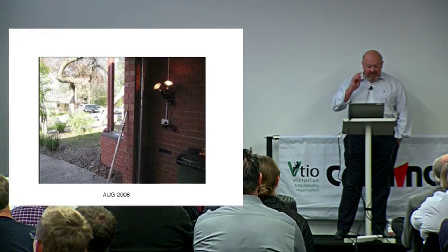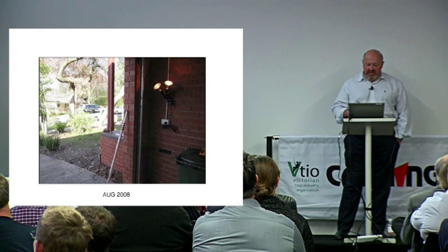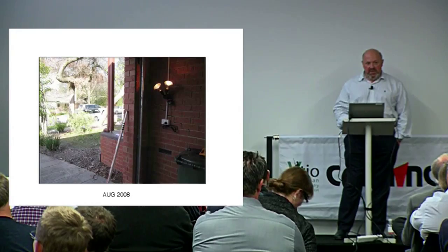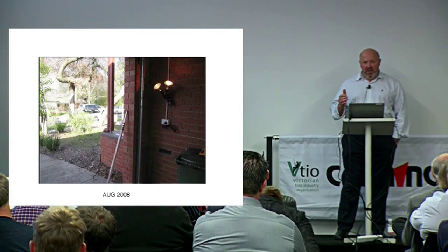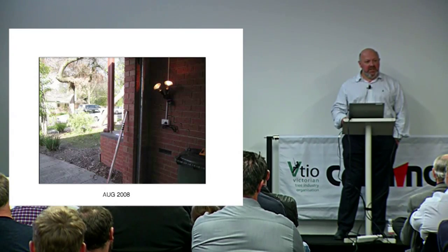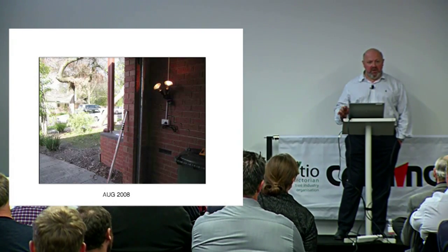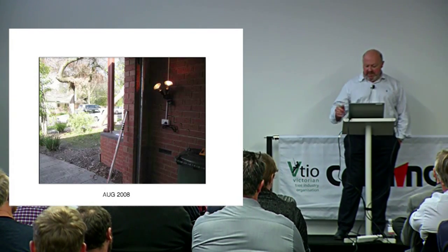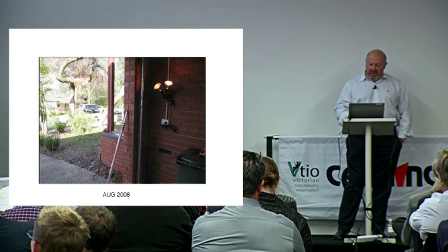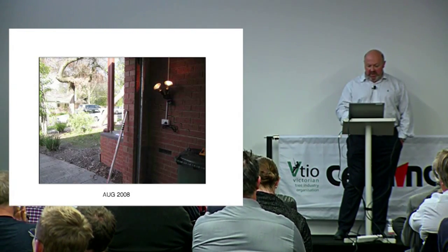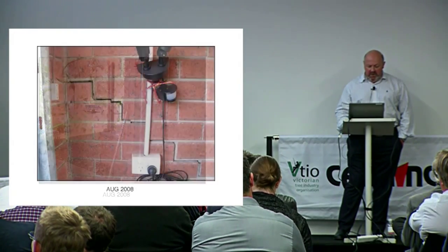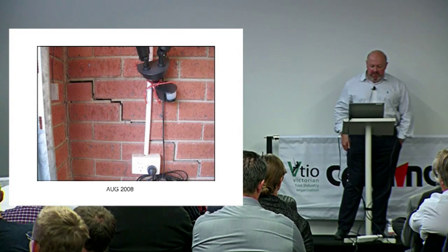Okay, this is just about finished. In the good old days, we used to get engaged by Housing Guarantee Fund and insurance companies, and the funding was there to go back regularly to sites, and this is when that decade, or those 2 decades, is where we probably learned most about cracking buildings because we got to go back on a regular basis. This is a classic where we had some step cracking in the garage. Some vegetation in the front was causing some soil dryness. That was the crack when we first looked at the building.